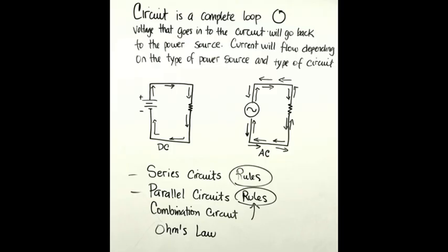So it would be 1 divided by R1 plus 1 divided by R2 plus 1 divided by R3 plus 1 divided by R4, and however many resistors we have. So if we have more than 3 resistors, but we have the resistor values, we would use formula number 3 to solve for the total resistance.